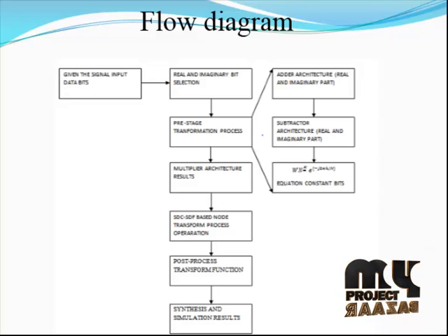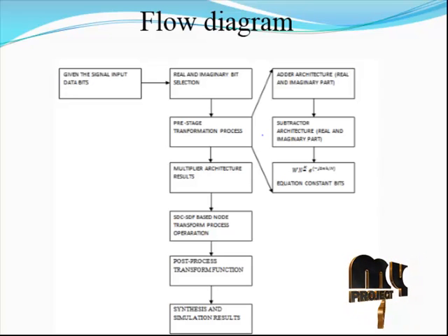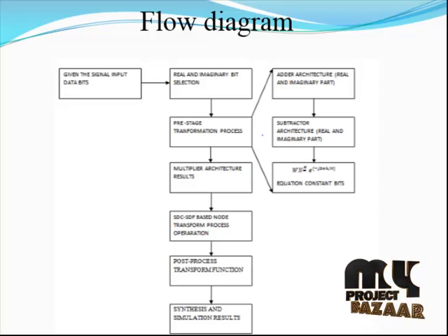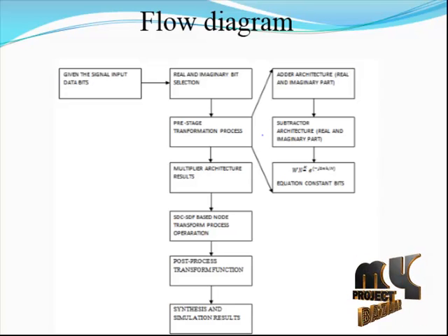The multiplier requirement is approximate. The proposed design preserves the Radix-2 nature and achieves 100% multiplier utilization, while the other Radix-2 designs only achieve 50% utilization. Furthermore, the high Radix designs require more complex adders than the proposed design and can only process FFT whose size is a power of its high Radix. The 128-point FFT cannot be directly mapped to either high Radix design, but the Radix-2 design can. Beyond the scope of this brief, the mixed Radix design can implement the 128-point FFT with relatively complex control logic.